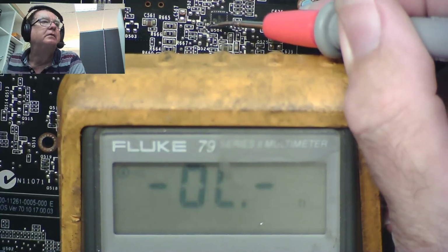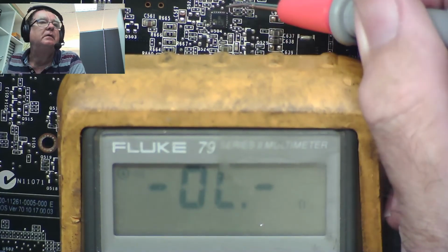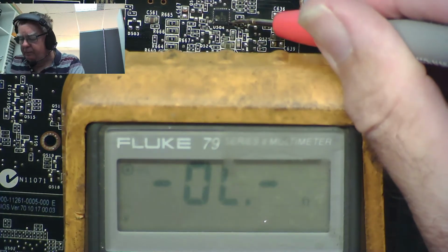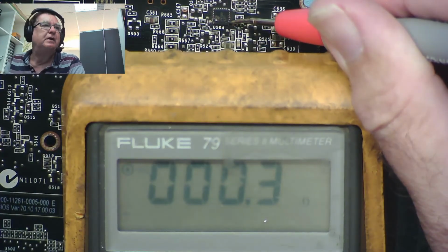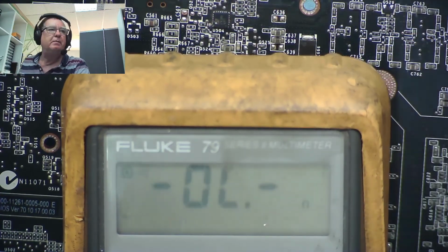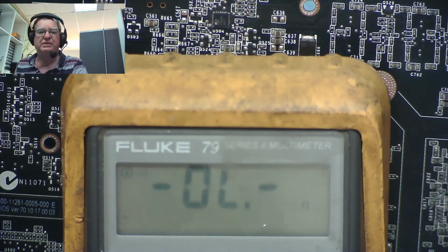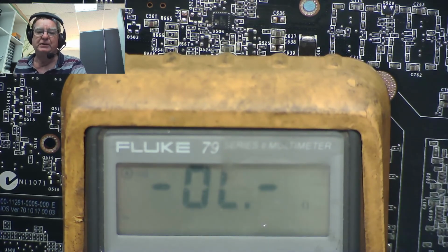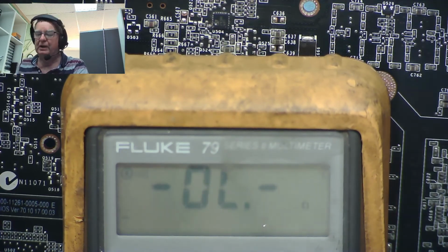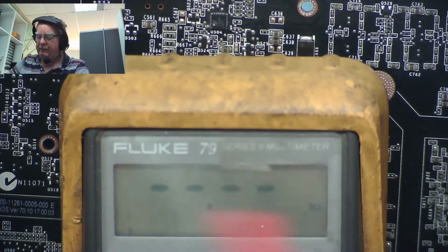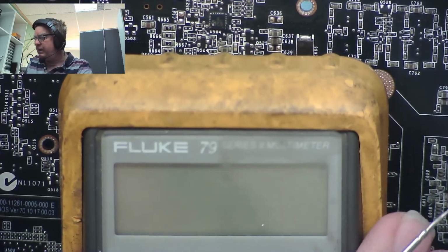Count the pins. This was 18. Pin 1's by the dot, so I'm sure it's over here. Yeah, it is. Yeah, that also reads extremely low resistance. So we can be pretty sure now our 0 ohm resistor, or whatever it is, is the same as the other channel. We've got the same resistance from the controller chip to the gate on both phases.